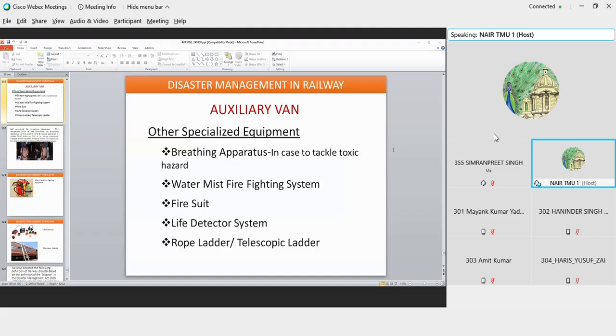Why is jacking of props done in a crane although it has sufficient counterweights? You see, when a 140-ton crane comes, it is on a gauge of 1676 wheel. So you are basically trying to increase the area which is taking the load.